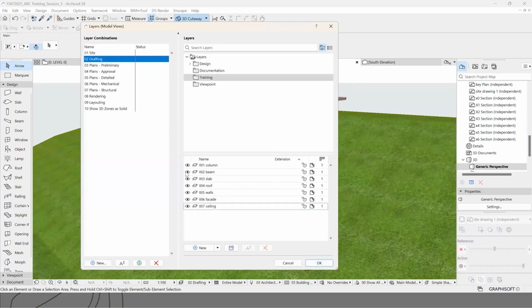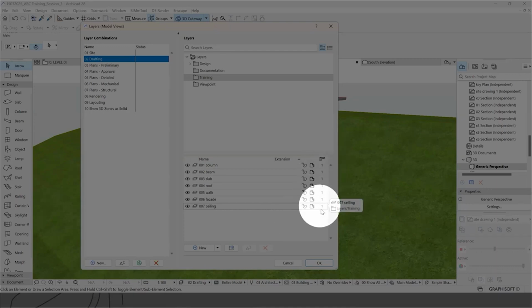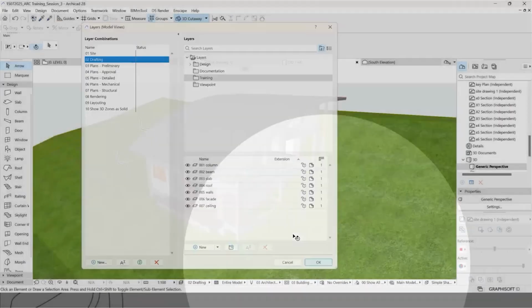This is how we create the layers. You also have the option of hiding a layer, locking a layer, or seeing it in wireframe for 3D. You can also work on the intersection details. If the same numbers are there, then they will be connecting, but that is not for right now. Just keep it always at 1 unless you want elements to be disconnected. So you give OK; that was creating the layers.